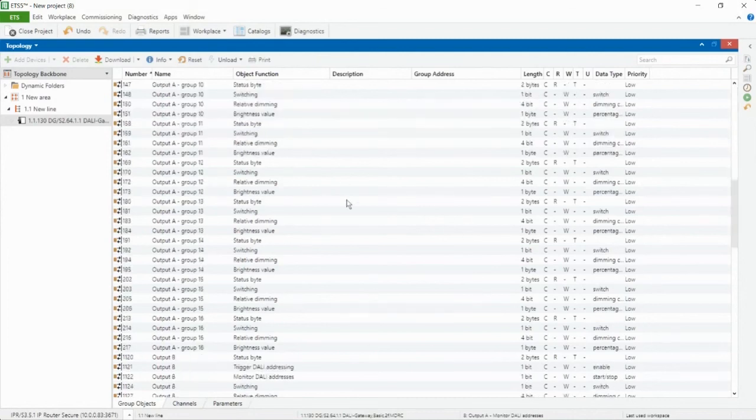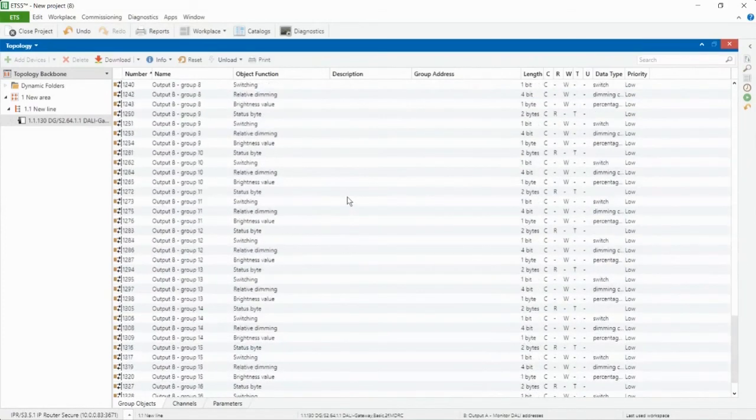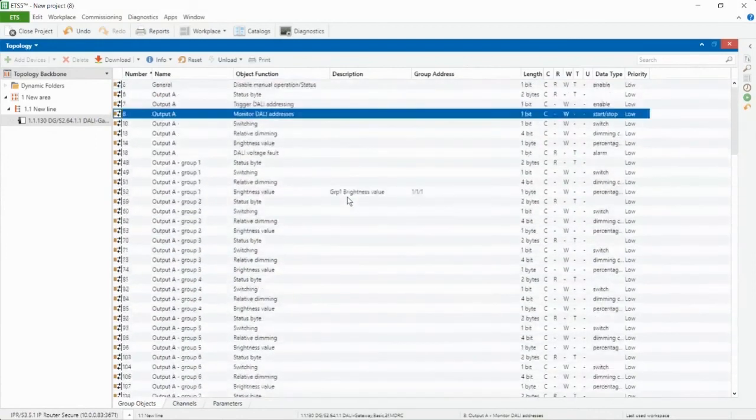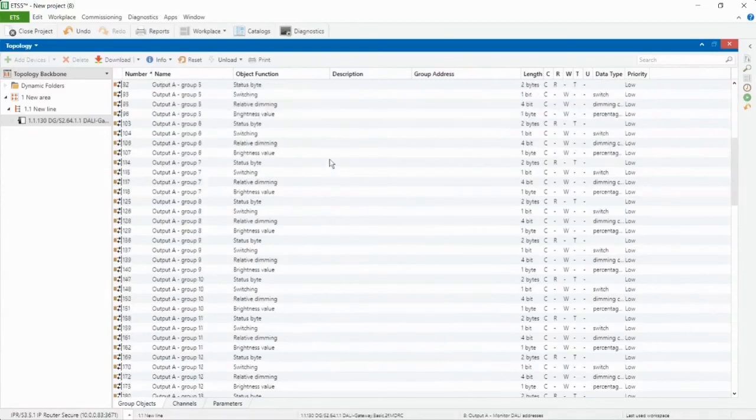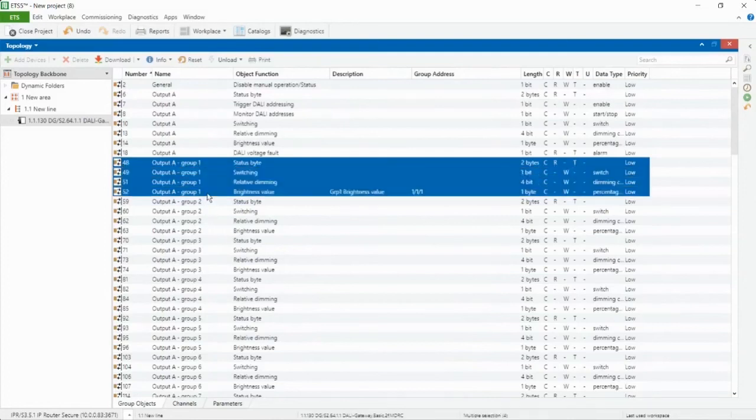So you can see here is where I'm going to program KNX as to how I work it. And like I said, there are plenty of connections here to get right and get wrong. Look at all that now. That's a lot of connections just for 2 lines, just with 16 groups per line. If I want to take it into individual devices, that's going to blow out very quickly because I will have all those settings. I'll have 4 connections for every lamp that I connect to if I do it individually. So if I have 64 devices on a line, that's a lot of fittings to connect together. So it's quicker to do this way.